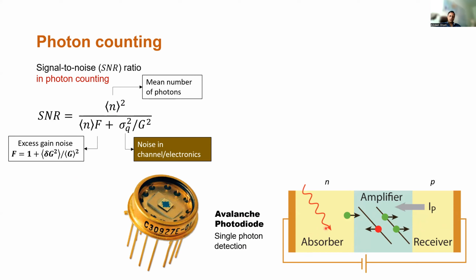In the process, the electron goes from one side to the other and it recombines randomly, in a very stochastic manner, with the hole. And this is essentially limiting. I told you in the beginning that the gain is given by the lifetime, and the lifetime becomes a stochastic quantity because the recombination of the electron and holes in this region becomes a stochastic quantity. And that is the origin of gain noise, which limits the performance of the avalanche photodiodes that we have in